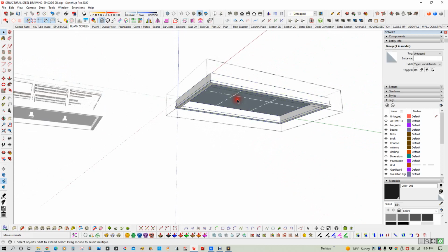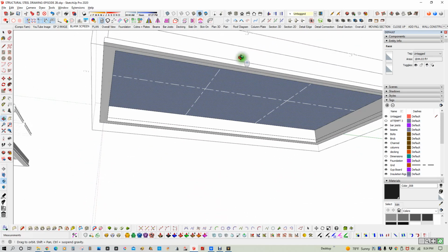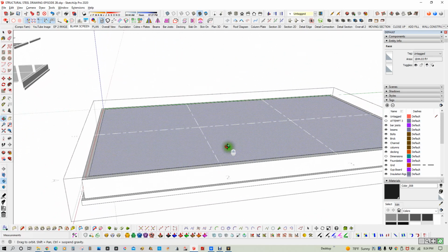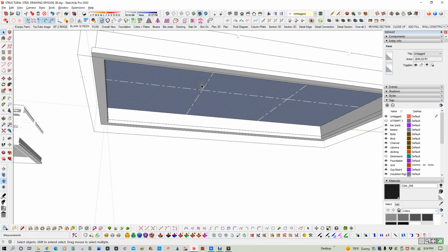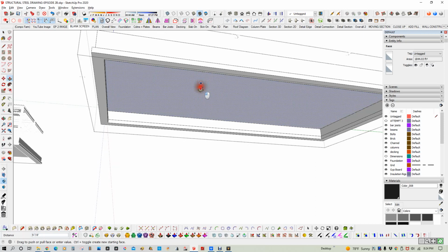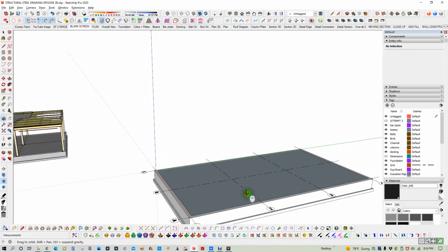There's probably no thickness to this foundation slab. And you can tell that by double clicking or whatever on the one side of the slab. And if you can see that highlighted on both sides, you know there's no thickness. So push pull. I'm going to tap Control to keep the outside face there. When you push pull, sometimes you can eliminate the original face and have to go back and put that back in. So if you tap Control, it basically copies the first face and allows you to drag a copy out, if you will.